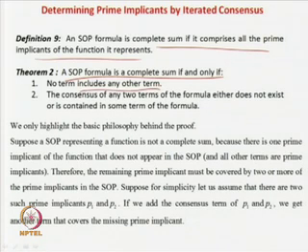That is very obvious, by definition only, because if any term is totally included in any other term, then that has to be eliminated, and by the definition of prime implicant, it is not a prime implicant. Like if there is a term called P and all the minterms inside it are included in another term called P prime, or say Q, then it is not prime. So if P is a term, Q is a term.